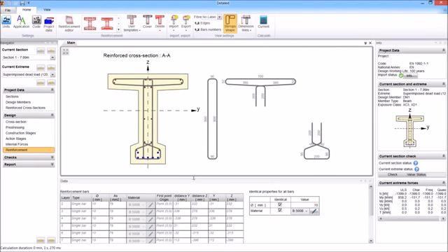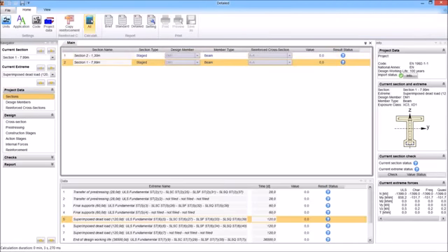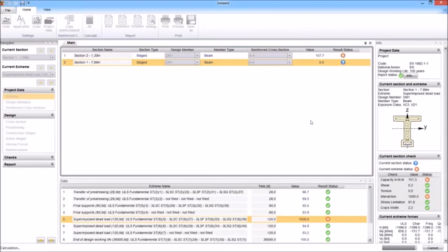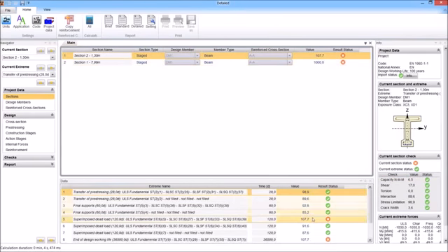Now the program generated these stirrups, and we can go back to sections and we can calculate it all. Now we will see if it improved, and it seems that it did. The non-pre-stressed reinforcement improved the capacity by, let's say, 9%, which is not satisfactory. We still have 101, and here we have 107 for shear, which is still not satisfactory.